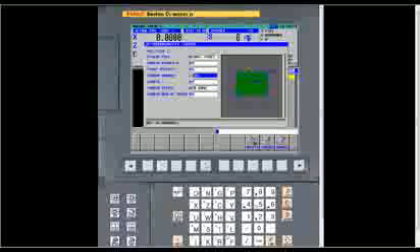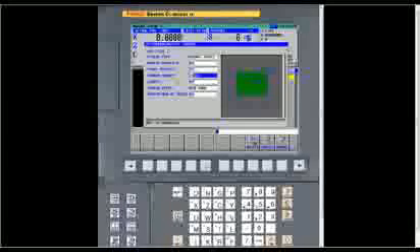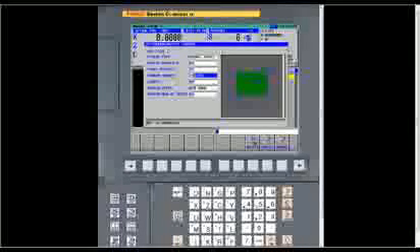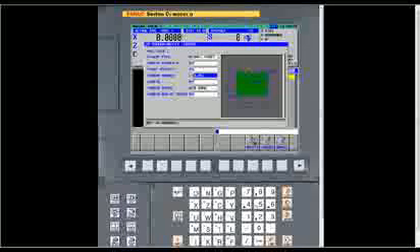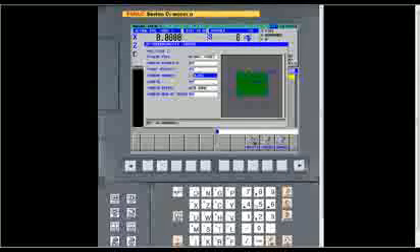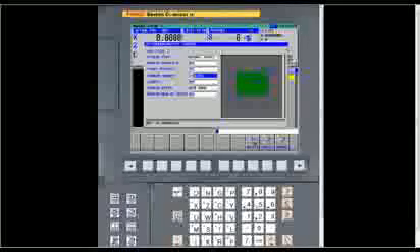Also, another thing I want to tell you, whenever there's a number associated with an answer in a Manual Guide i field, the control will act as a calculator. So if we go down here and go 1 divided by 16, and then input that, it'll do the math for you. So it's capable of doing any math function that you know the symbol for, whether it's division, multiplication, adding, subtraction, tangent, cotangent. It'll do all that figuring for you. So that's important that you know that too.